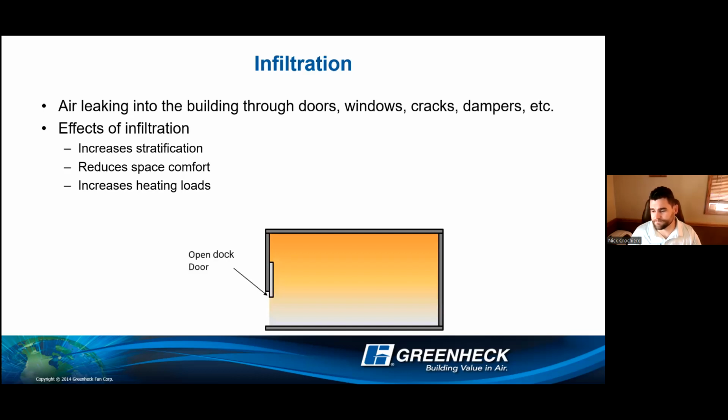Again, that diagram showing the open dock door, cold air infiltration coming into the space, then mixing where your warm air is forced to the ceiling. So say if you are heating with maybe an air turnover unit or something like that, that's heating more towards the ceiling, not directly blasting down, it will most likely mix and have that hot air pocket above with cold air infiltration below through the doors.